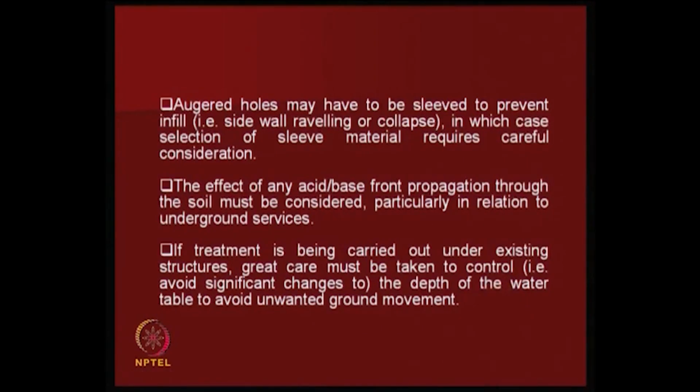You can remove water in one place, but at the same time, where it is important, you should maintain the water table by putting water back, at least close to the foundation area, so that we do not get an increase in effective stress below the foundation. We only want water removal somewhere else, not beneath the foundation. So one should be very careful in removing the water, particularly close to foundations.